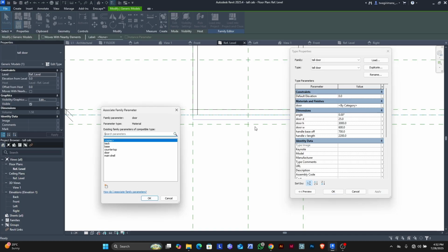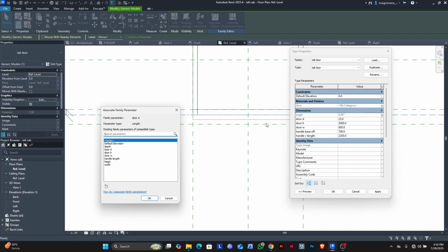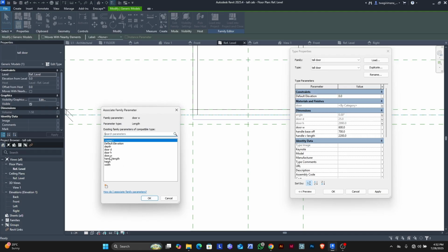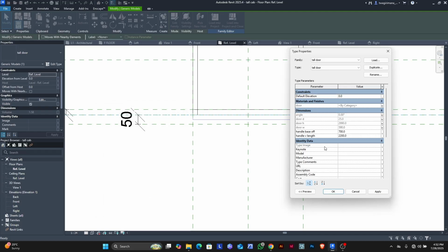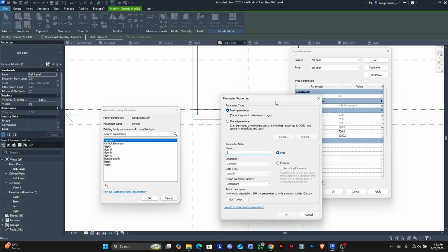So this door will still be the door here, the angle parameters will keep it. So we will keep the door depth as the door depth, the door height as the door height, okay. So the door width as the door width, have to keep everything. And since you don't have them here, you have to create them as the new parameters.